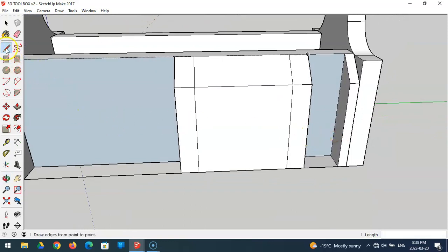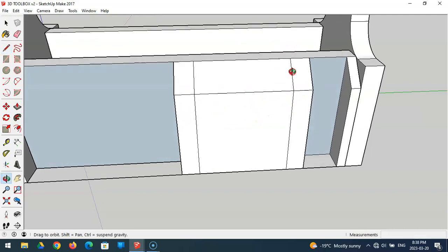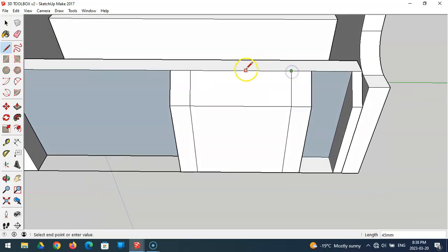Now let's do another one. We can start anywhere. If we wanted to, we can even start up here. So let's go 40, enter, find 40, and then come parallel down. Remember, you want it to snap. In this case, that's kind of a purplish pink line. Come all the way on the blue to the bottom. Then we're going to type in 20. That was the wrong one. Let's try that again.